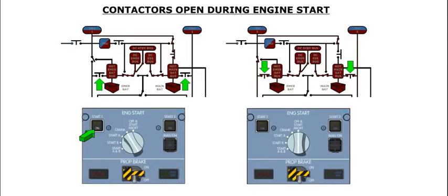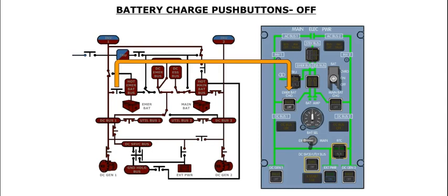The MFC will also open both battery charger contactors during engine start. The contactors will close when the start selector is out of the start or crank position. When a battery charger push button is released out, the associated charge contactor opens, and the off caption illuminates in the push button.